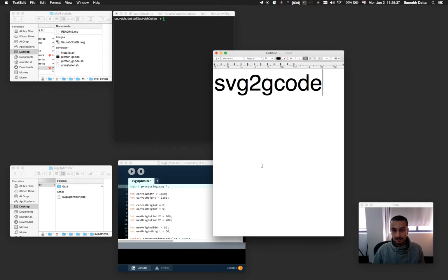This is basically what it does: it uses this library underneath, and then whatever G code is generated by this utility, it reformats according to my plotter's needs. For example, I want to home my plotter after every cycle of G code. Say I make my G code, and then I want the plotter to automatically reset itself to the home position. So I incorporate the homing cycle G code commands on top of every G code file, and this doesn't give me that, so I insert it in there.